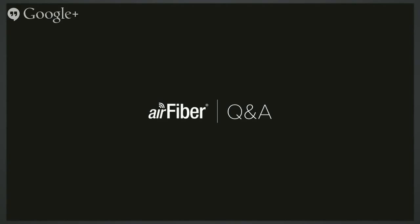The AF5 really doesn't have that issue. 5 gigahertz is really not affected by rain. I'm not going to say that if a glacier came between the two units there might not be an issue, but short of that, you really wouldn't expect to see any sort of issue when it comes to fog, humidity, anything like that with the 5 gig product.